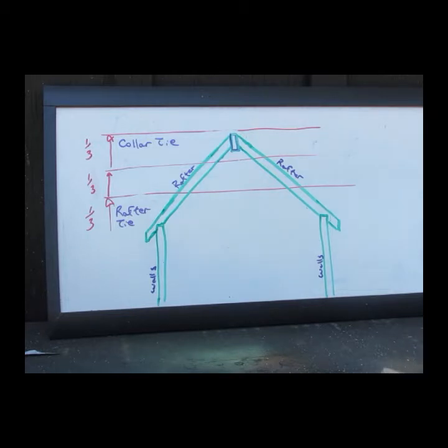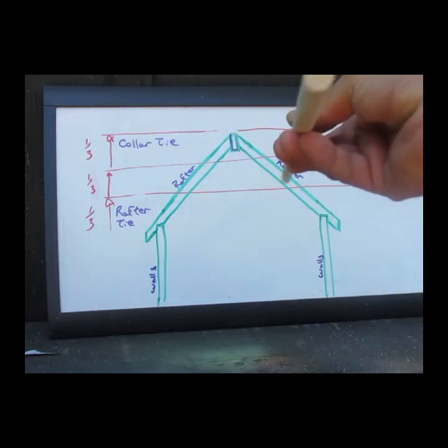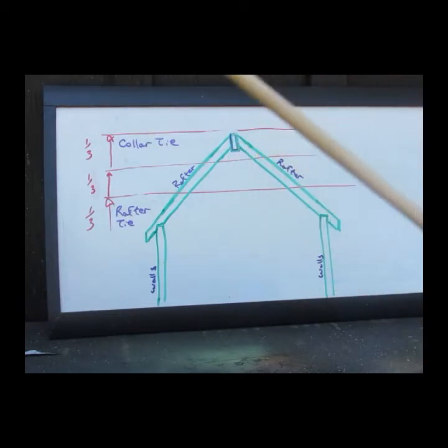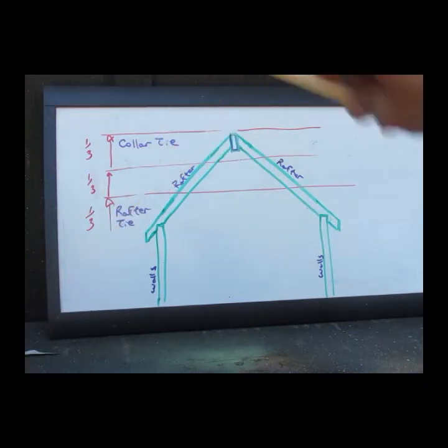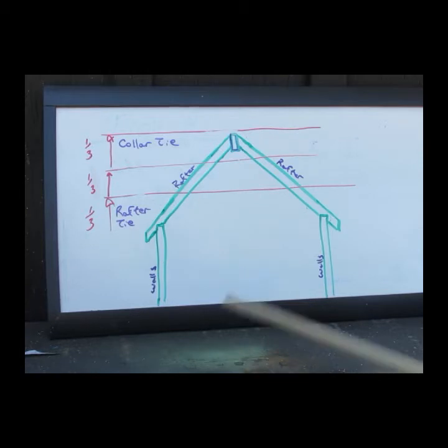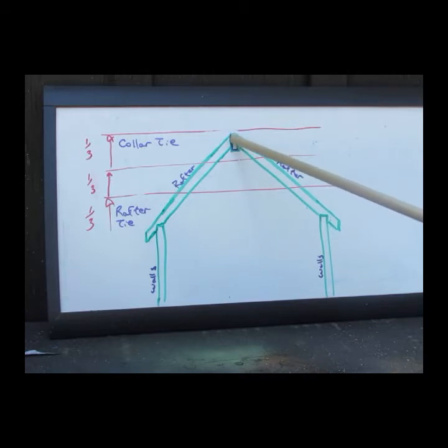And then if you have a beam that runs this way, you would put a rafter here, then you put a rafter on the other side, basically putting up your 2x4s to meet the rafter at the right angle. So you'll have to cut the end of the 2x4 at the right angle to be fastened to the center beam, and a bird's mouth on the bottom so that it locks in place on the wall.